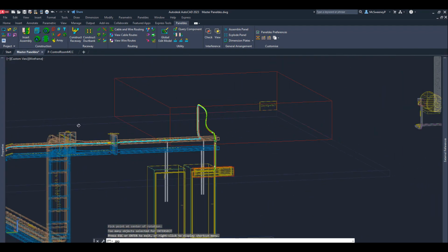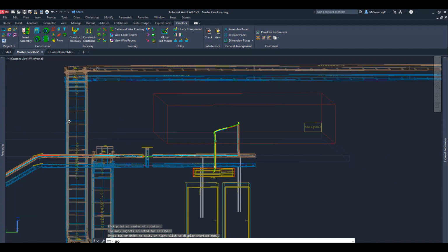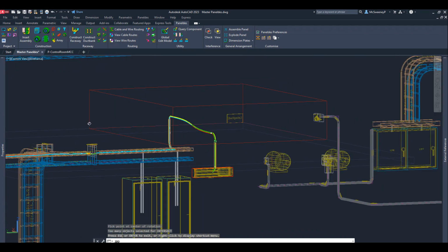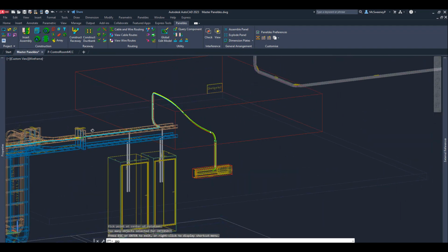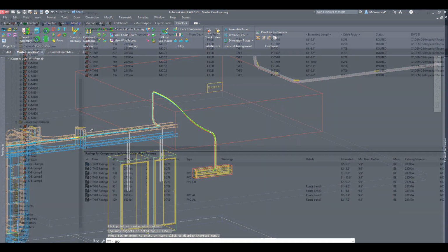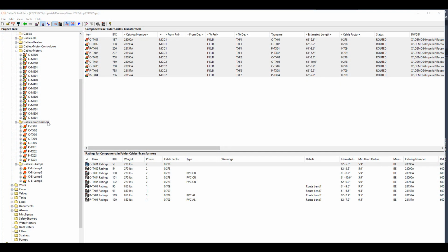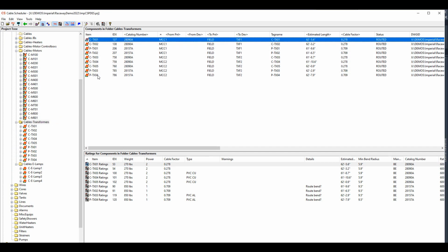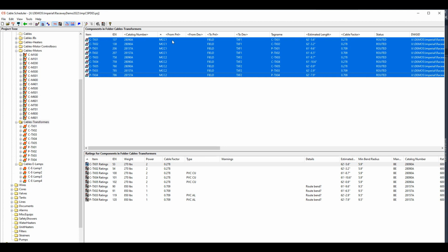Note the route uses splines to transition around corners smoothly. Pull zones can often be devoid of raceway. You could use a pull zone in a ceiling, a manhole, in a ship's or offshore platform's cableways, or in any vehicle. Another special feature of Paneldes routing is the ability to define a no-go area for cables.